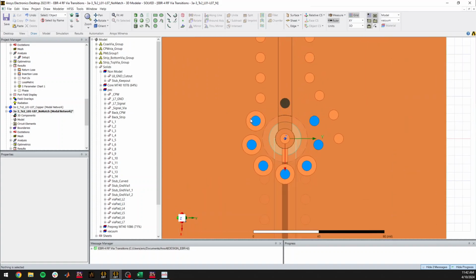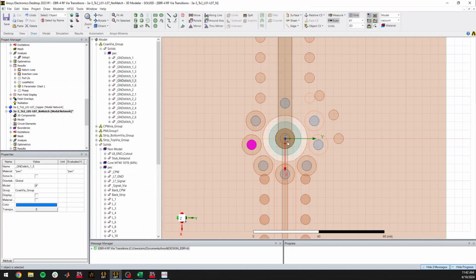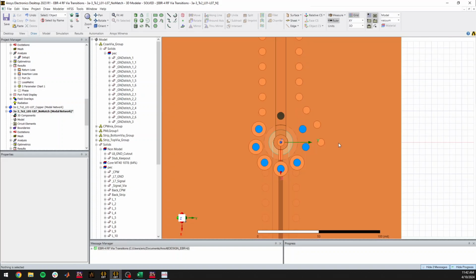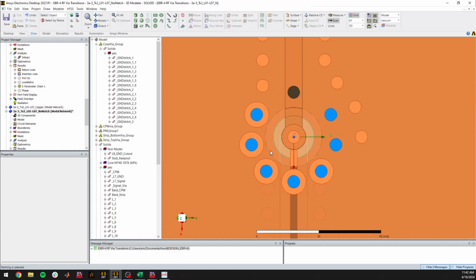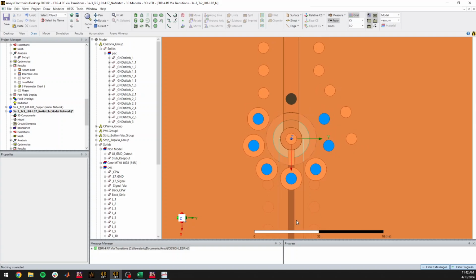So the spacing, or the effective diameter of this relative to the center, is something that can be designed as like a parametric. You can make that parametric and sweep the spacing, see what's feasible. Often you're working within the constraints of DRC and DFM, where these vias can't be super close from like a hole to copper clearance perspective. Also, you're looking to have some tolerance, like I was talking about earlier, where this doesn't have to be spot on every single time to have good performance.